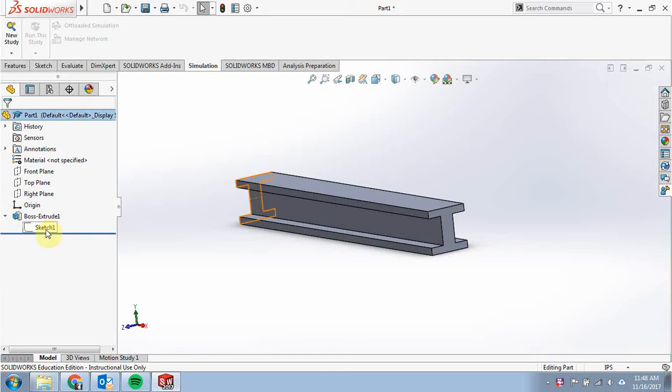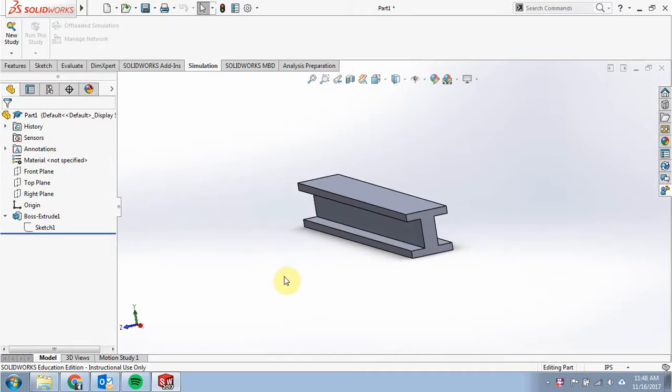I just made a sketch here on the side of the I shape, and then I extruded it. If you take a look, we have about 6 inches wide and tall, only 1 inch on these, and it's 48 inches long. So in order to take this and actually produce the simulation, we're going to be taking a look at some of our tabs up here, or our ribbons, as you might also hear out in the world. And we're going to click on our simulation one.